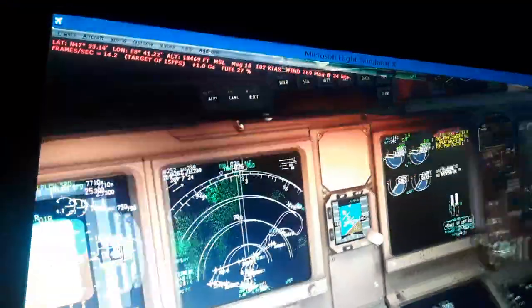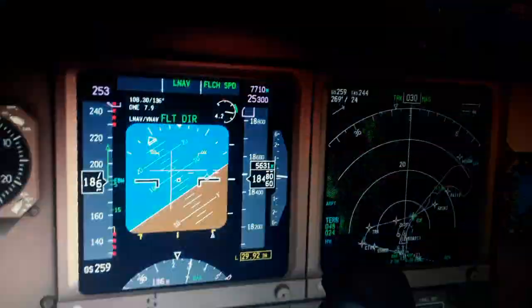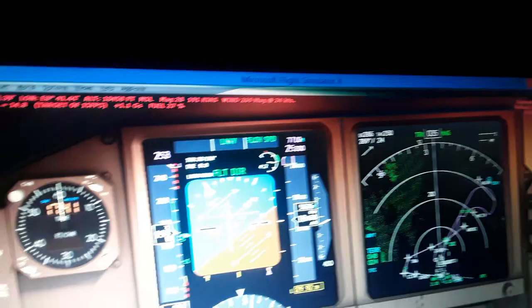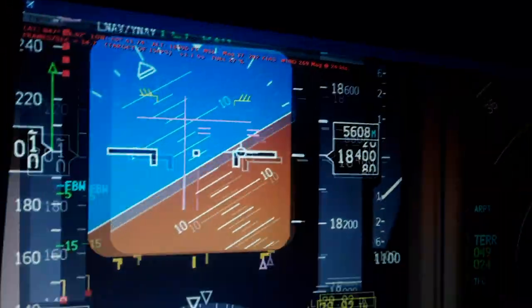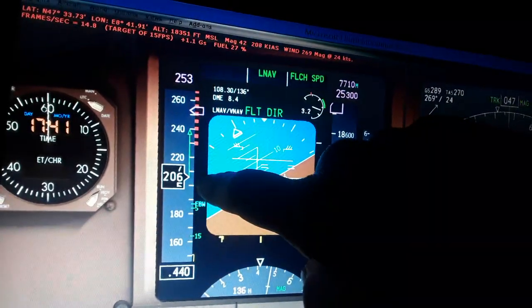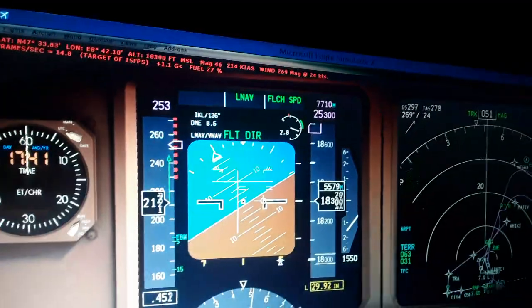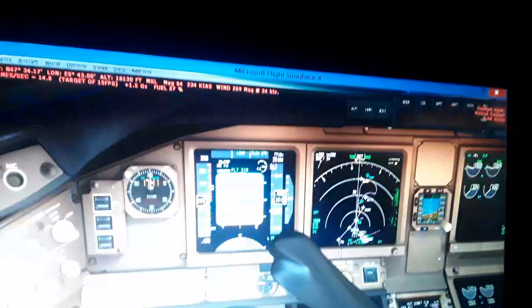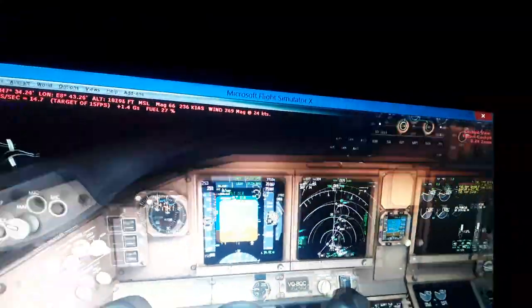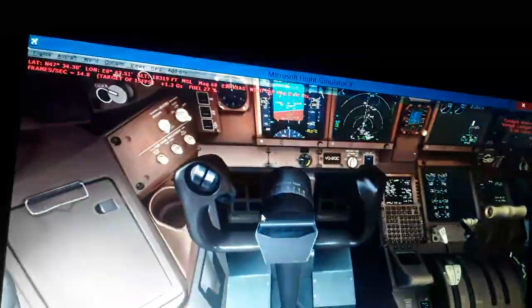So you can see we have reached the stall margin here. The stall is gonna make the aircraft fall, so you have to use the stall avoidance. You can level off. Over here you have the limit for the flaps, this red limit. So you can descend a little bit, increase your speed, and then climb again. So we're gonna cross the next waypoint now.